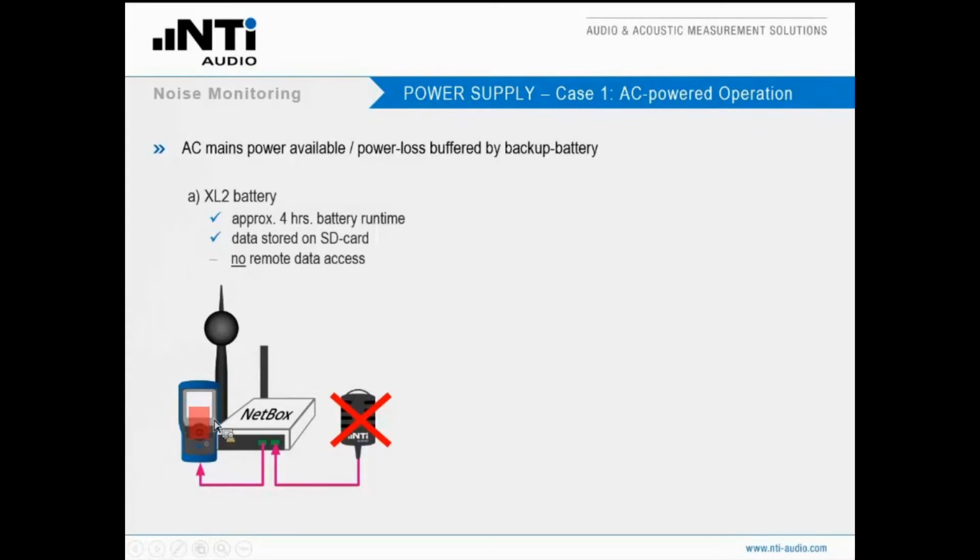Keep in mind, please, that this internal battery only operates the XL2 for up to 4 hours. The data are safe on the SD card, but the battery does not power the netbox, and for that reason, during that downtime, you have no connection, no remote access to your noise monitor.